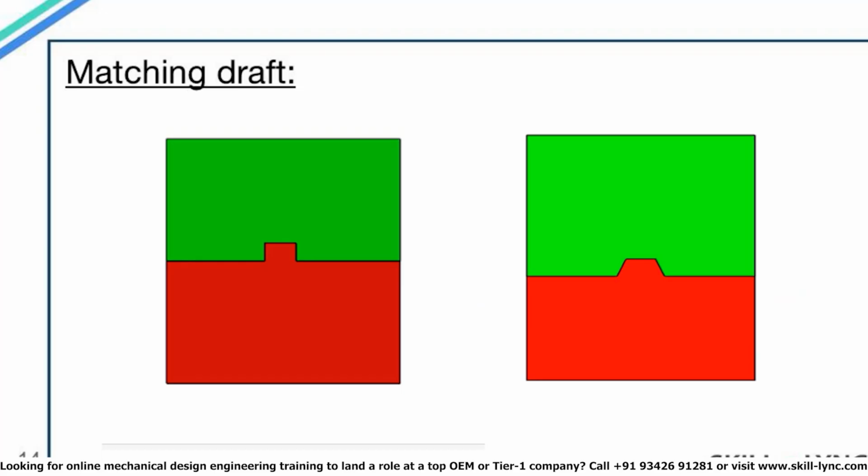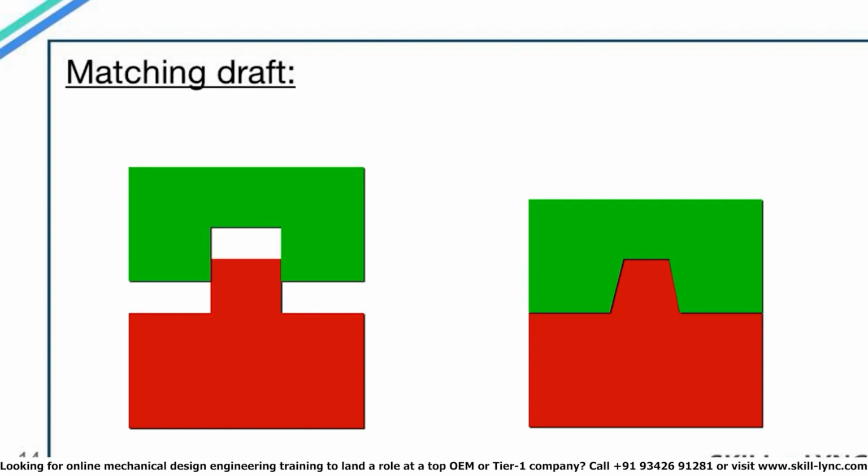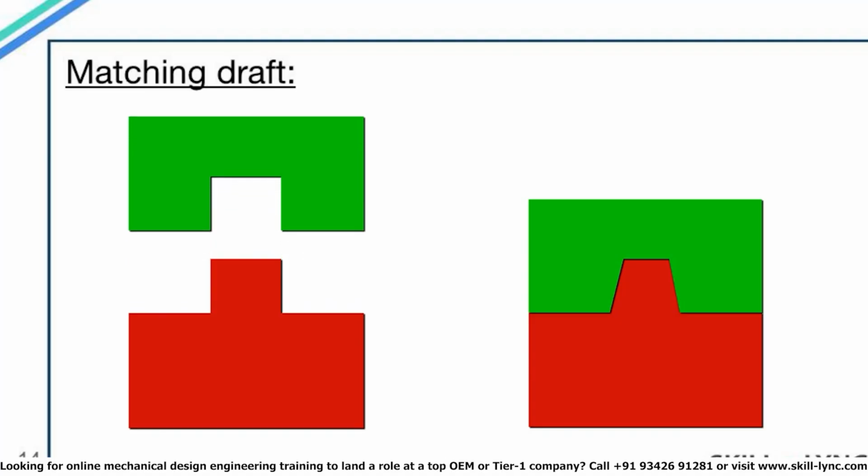So here let's focus on the side view of the mold block for both the models. In the left case, where we have a 90-degree cut groove, when the core block tries to move in the downwards direction after the plastic material is solidified, the core steel block will rub against the steel cavity block as you can see in the animation.